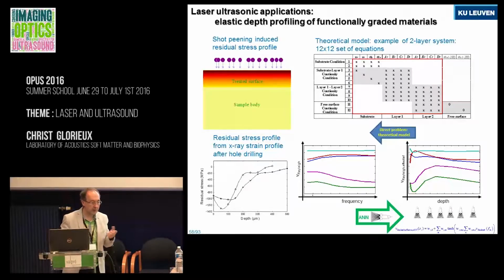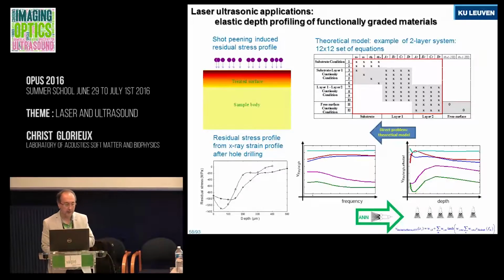when the components are used in practice, there is often tensile stress. The samples are pulled, and so you can break them by pulling. You cannot break them by compressing them. So by adding some additional compression, when you pull them, they actually go to normal. You make them stronger by pre-compressing them, and you can do that by bombarding them with small balls, by shot peening. But the shot peening only helps at the top because that's where the balls are impacting. So people are interested in how deep the profile of the stress is.